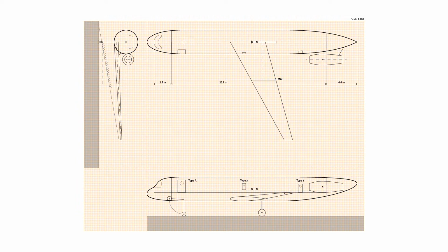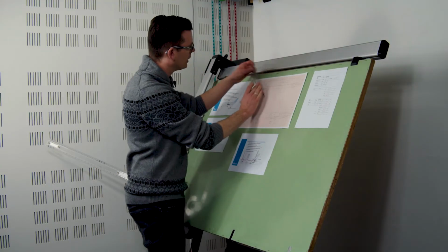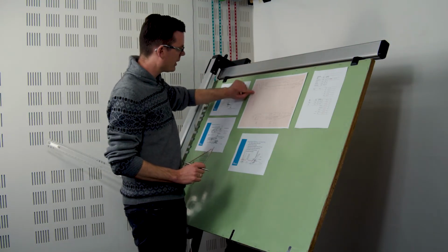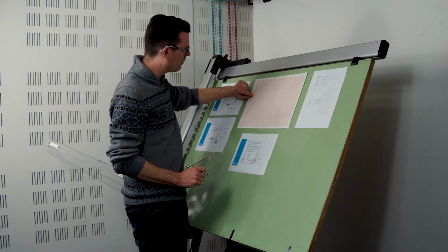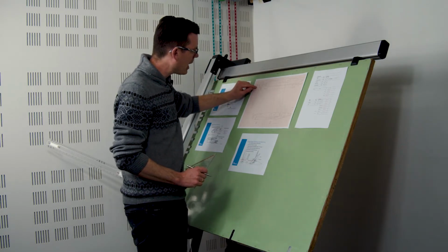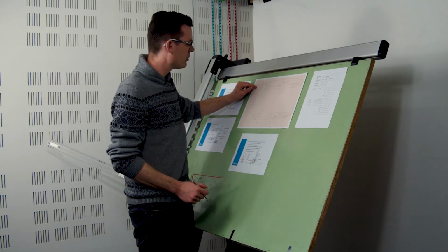And drawing a notional line again, saying, okay, the wheel needs to be below this line. Well, you can see this diagonal line here, the 10-degree line, actually intersects with the main landing gear axle at about 1 meter away from the center line.